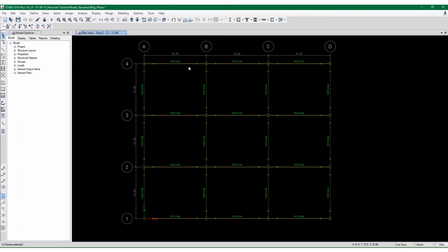I know ultimately I will have a deeper beam framing into a shallow beam for this example, but in the real world, even though that can occur, I would make the beam depths at least the same depth if necessary. Most of the time I will always do that. In an unusual situation, I'll accept a deep beam framing into a shallow beam and adjust the connection accordingly.